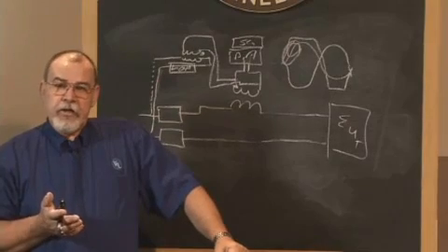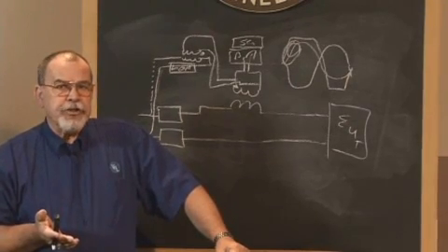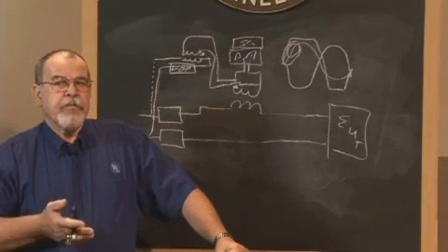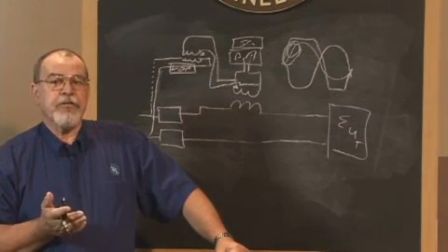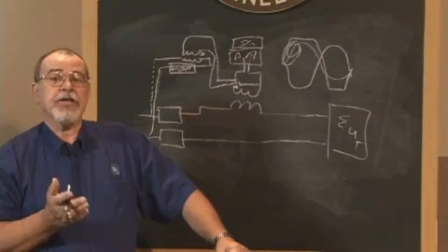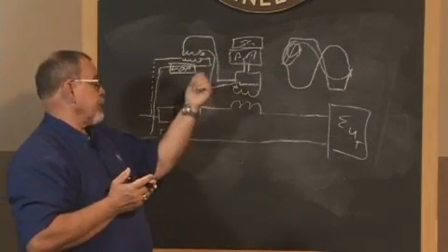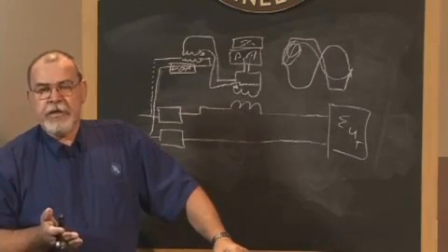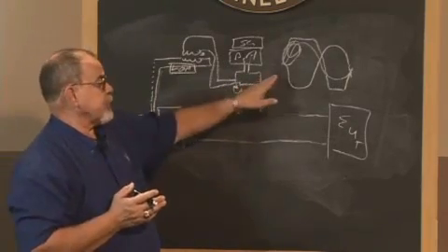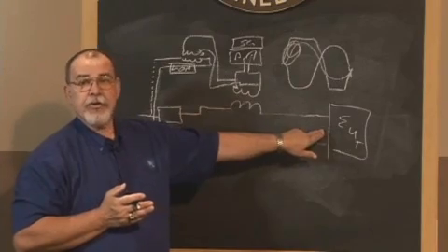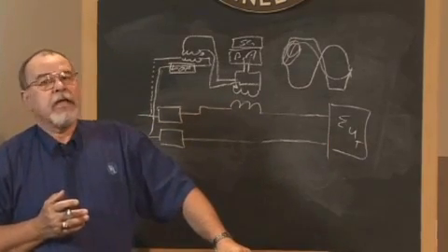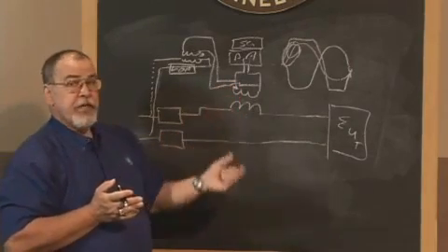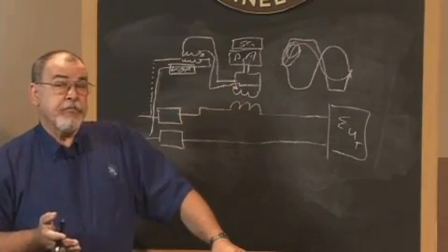Now, quite frequently you don't notice this. You get started with the test and everything is happy, and 2 or 3 seconds later it suddenly trips because the phase variance has changed ever so slightly to get to the point where this power amplifier shuts down. You'll never get through the test. You have to be able to cancel with the waveform identical to the test article. Okay? Without that cancellation, you don't get there. So the circuit that's in the manual doesn't quite do the trick.